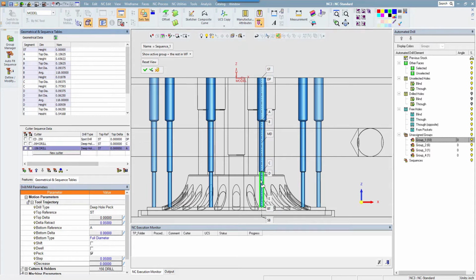Now, this 062 at the bottom here, that would wander if we tried to drill it, so you'd probably wire that or drill it from the top. So that's something we're going to leave alone. In this case, we're just doing the back drill.